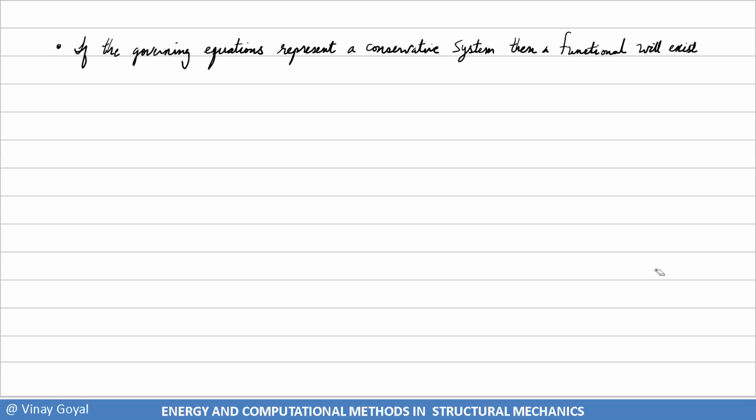So the first step in the process is to multiply the governing equation by a test function. And that test function has to satisfy the boundary conditions of the problem. So I'm going to start with this, multiply both sides by a test function which satisfies the boundary conditions of the problem, meaning if I have any essential boundary conditions, I want to make sure that V is 0 at that boundary because I'm going to treat this like del W basically.